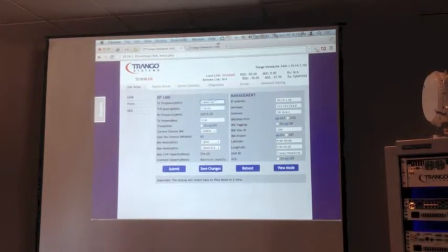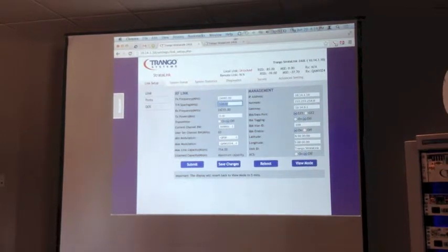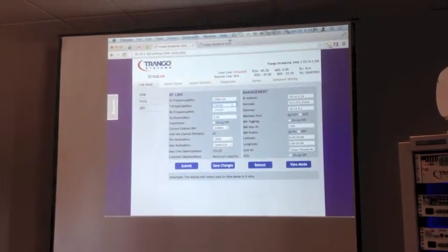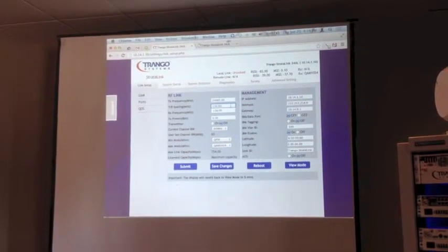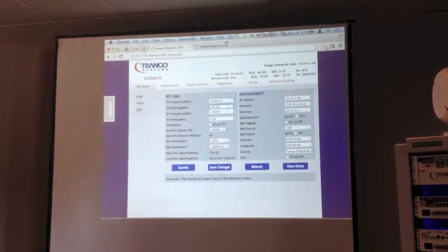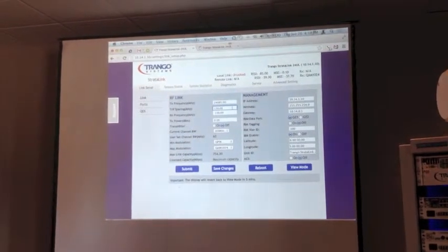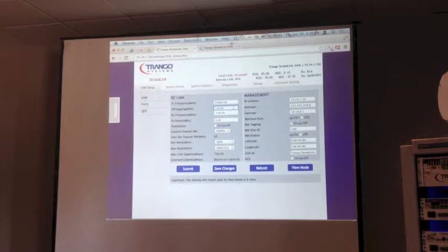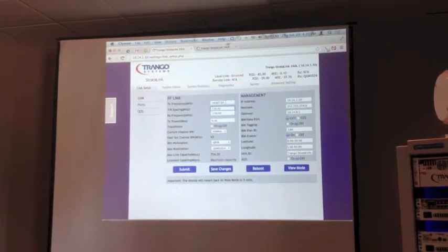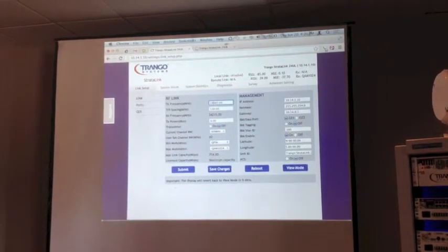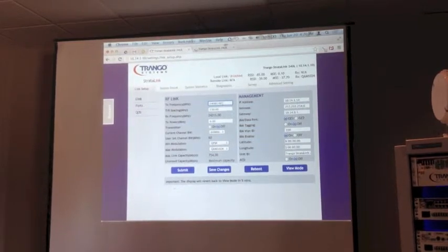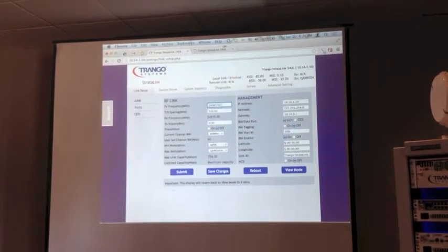So you put in your transmit frequency and you put in the spacing. Again, we would do this by default for you, but in the manual we list out some possible options for you to use, some suggested configurations. But you could put anything else in there. Effectively, if this is below 24,150, then we know that we need to add that to the other one. If it's above it, we know that we need to subtract to get to the receive.